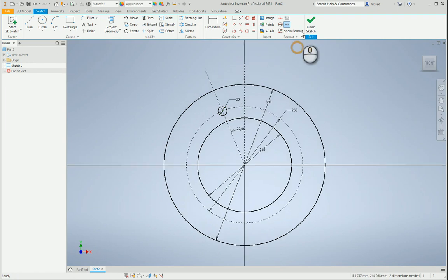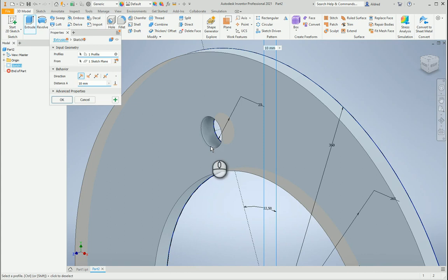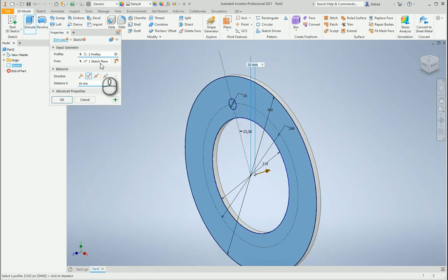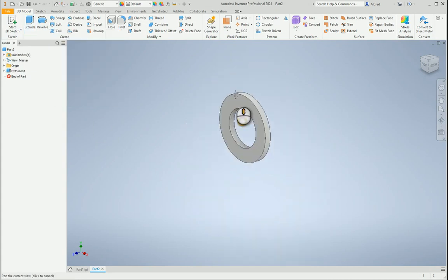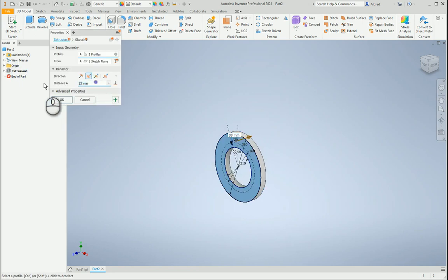Now the next thing we're going to do is extrude this, but we can extrude both the hole and the outside profile as well. And we're going to say this is thickness, or plate thickness, or flange thickness. Just notice that when you want to put two words, you can't have a space, you must put an underscore in there. Well, I like to put an underscore. Equals, let's make it 12. I want it to be 12.